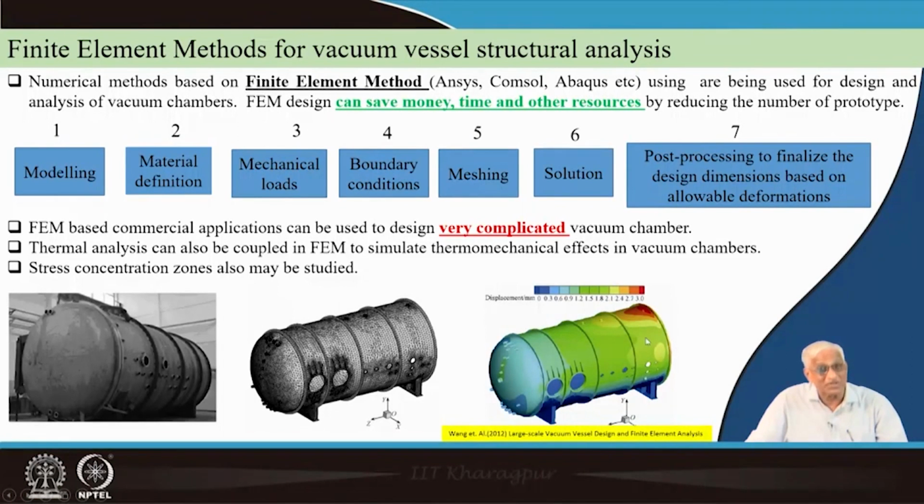But be careful to interpret the output. If you are not careful, you may make a mistake, and even a very smart employee may suddenly get into trouble, particularly while dealing with mechanical structures, if he has made any mistake in boundary conditions or meshing or initial input parameters. And when you connect a vacuum pump, suddenly it may implode. So instead of impressing the boss, you may lose your job. One should be very careful when using computerized models for thickness calculations. But they are very user friendly.